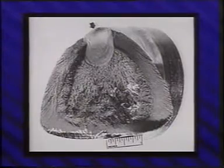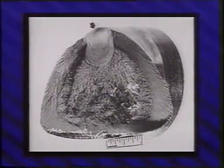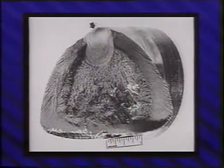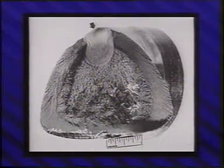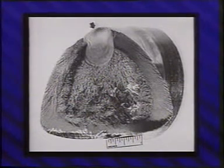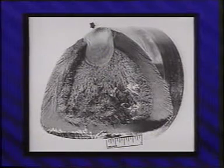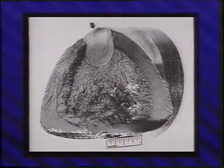Several different types of fractures may exist. In this induction-hardened axle, the fatigue origin was at the induction-hardened surface, heat-treated to about 46 HRC. The stress is concentrated in a fillet located at a change in the shaft diameter near a keyway runout. The fatigue crack gradually progressed around a large, roughly circular area.